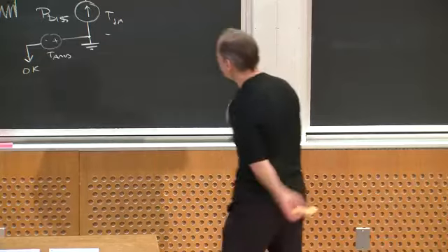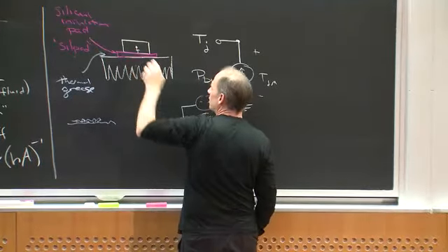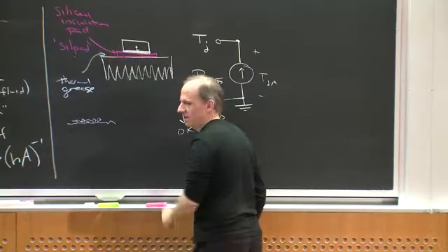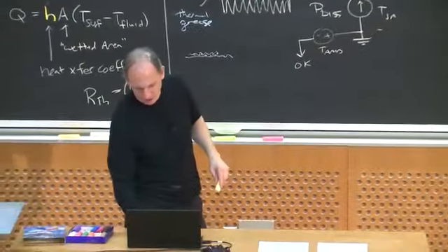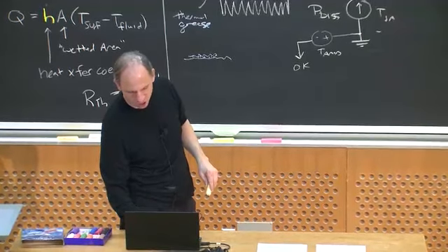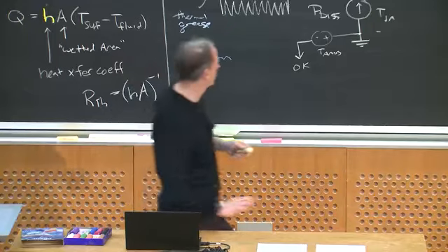Okay? Then I've got to transfer the heat to the surface of the device, right? Because I said, the heat's actually being dissipated inside, and there's some thermal resistance between where the heat's being dissipated inside the semiconductor to the actual case.